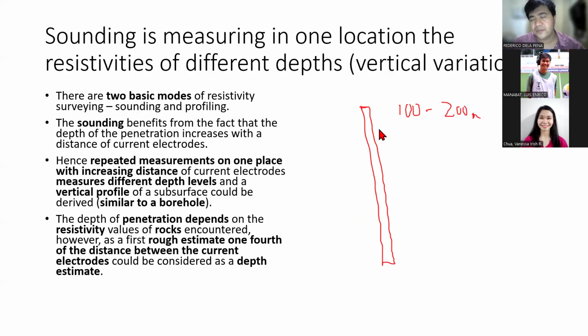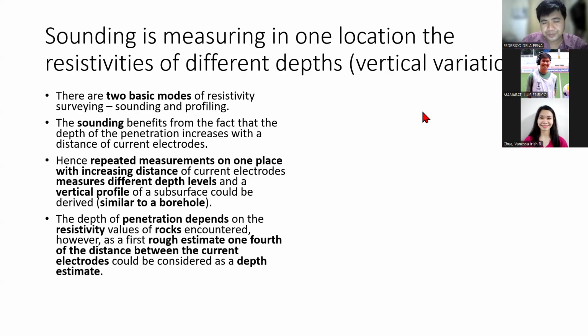And if you're going to try to do a resistivity survey that can penetrate that depth, you will need something like 400 meters to 800 meters of cable length, right? So it's a really large amount, lots of electric cables needed to reach that target depth.